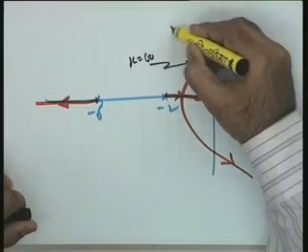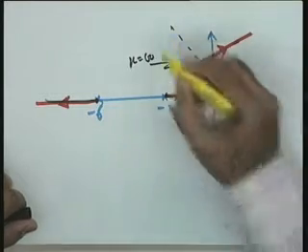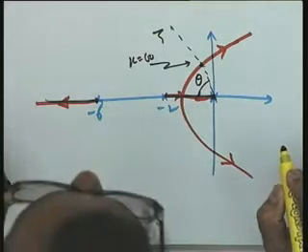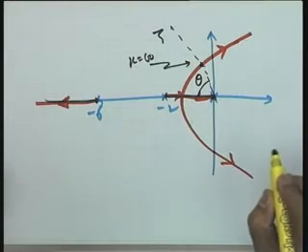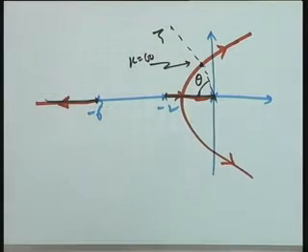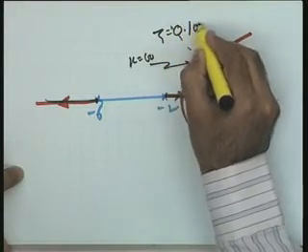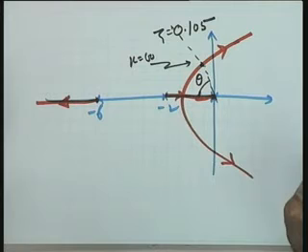So, what is this point corresponding to? This particular line gives you the value of zeta. If this angle is theta, then the value of zeta is given by cos theta. In this case, I take the help of my notes, I get zeta equal to 0.105. You had only the steady state accuracy requirement set by taking K equal to 1.